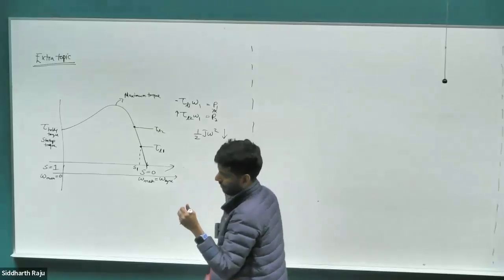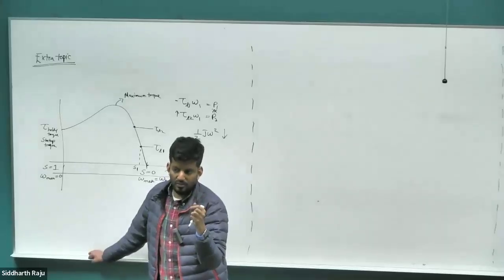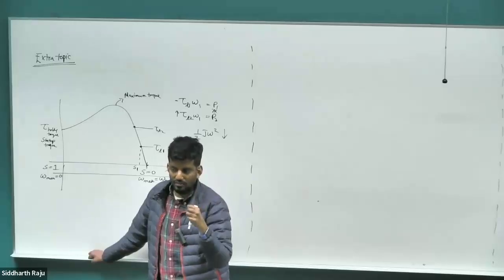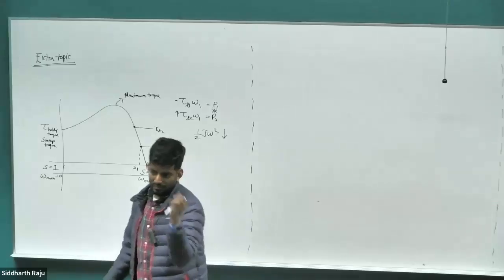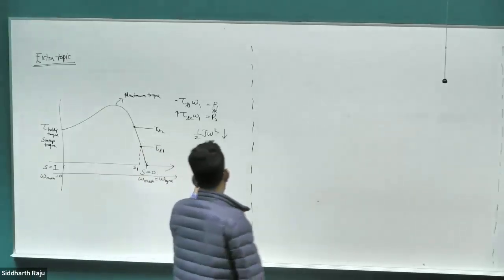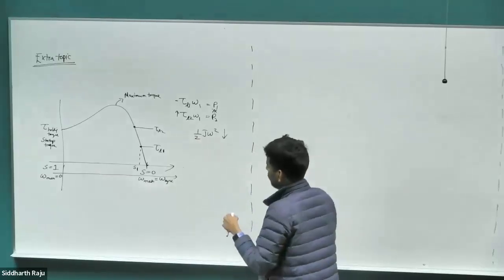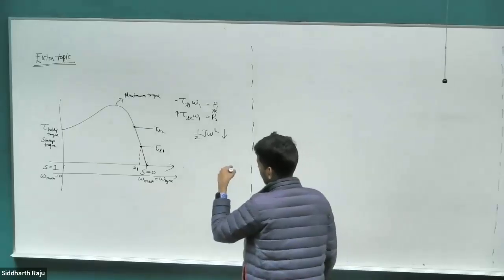Think of it as a capacitor with some voltage across it. So there is an associated energy, half C V squared. Now you put a resistor across that capacitor without putting any additional energy source into it. The current going out of the capacitor, basically a charge flowing out of the capacitor, is going to drain the capacitor voltage. Same thing happens here. The power going out of this inertial energy is going to drain the speed of the inertia.